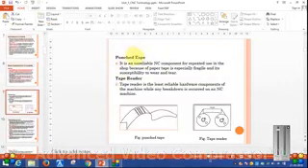Then next one is the punched paper. It is an unreliable NC component for repeated use in the shop because the paper tape is especially fragile and susceptible to wear and tear. Then the tape reader. The tape reader is the least reliable hardware component of NC machines, when any breakdown occurs on the NC machines. The punched paper tape is different for different operations and it is time consuming.